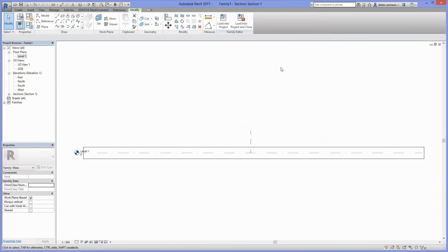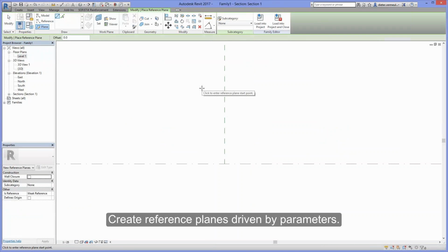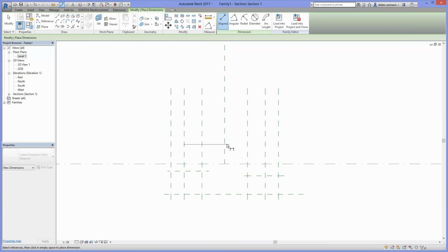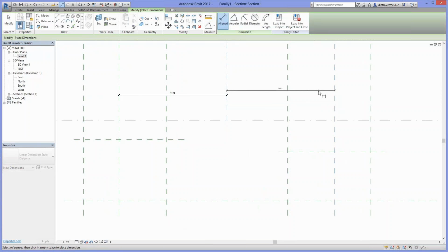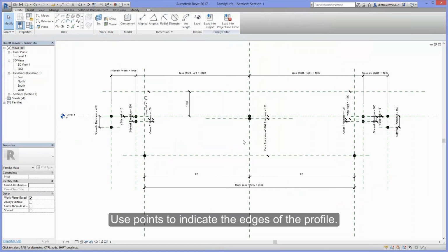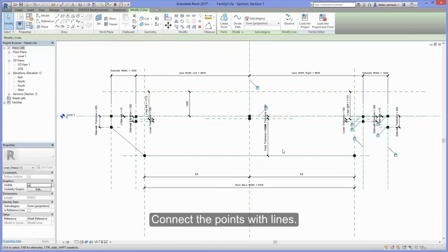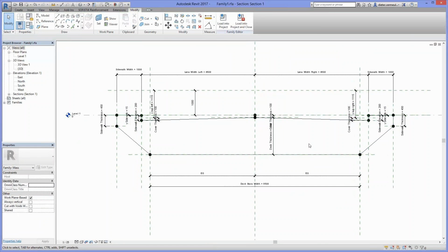And this is very similar to what you maybe do in AutoCAD, designing or drawing the typical cross-section of the bridge. However, here we are using constraints because it's parametrical modeling, and we are defining constraints, how it should behave, which dimension should change. If, for example, the left edge of the road changes, then automatically the right width of the road will change. The same is the super elevation. So we are defining constraints, we are defining points, and then we are defining links between these points.